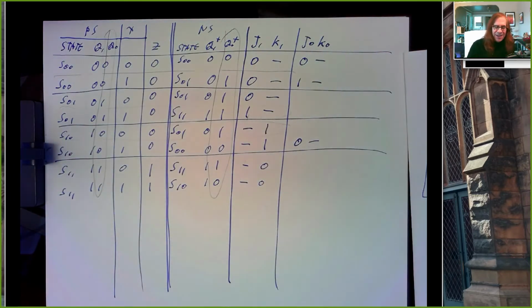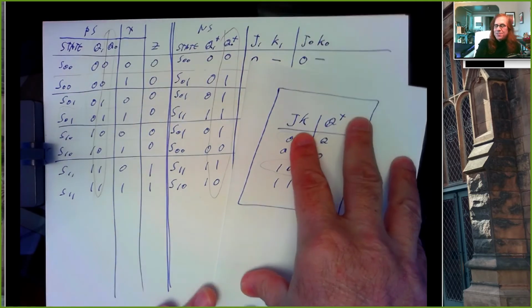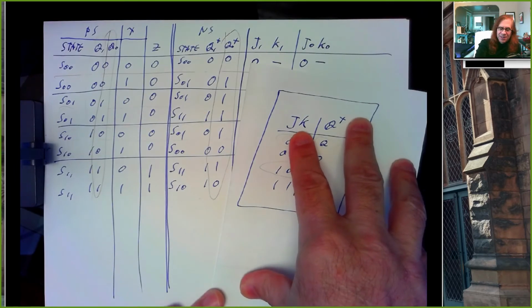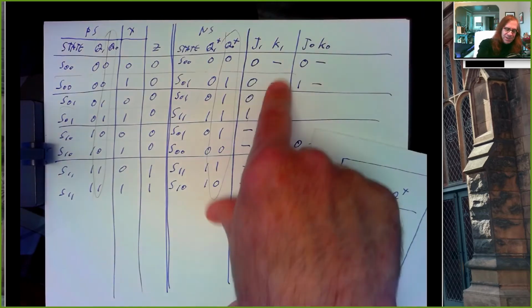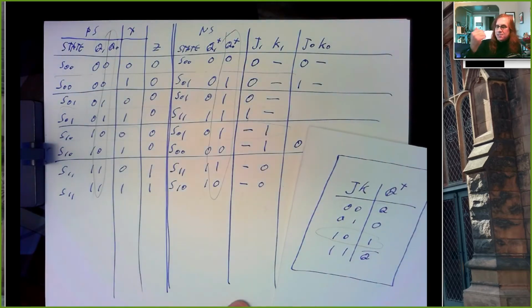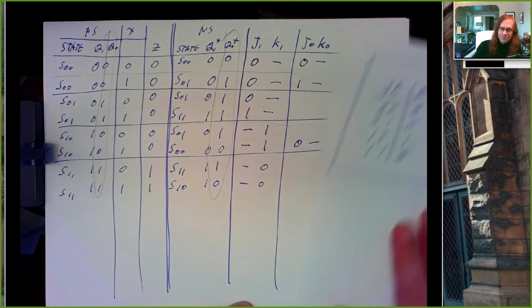So instead of having to remember what you did in the past and pull it out of the table, which is potentially error prone, and instead of having to reverse engineer the flip-flop, which is time consuming, let's just one time figure out how we set up J and K for different situations, and write that down in a table, and then we can refer to it.